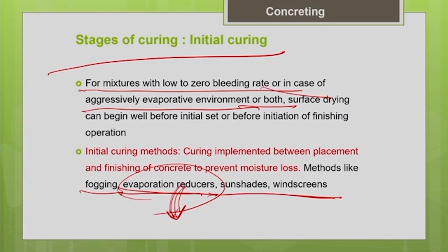Here surface drying can begin well before the initial setting or before the initiation of the finishing operation. So, in these cases the drying of the concrete can happen even before the initial setting of the concrete, or even before the starting of the finishing process. So, before the finishing process itself, this necessitates initial curing to prevent the surface drying of the concrete. So, what are these methods?